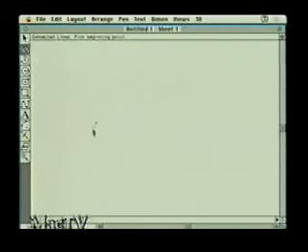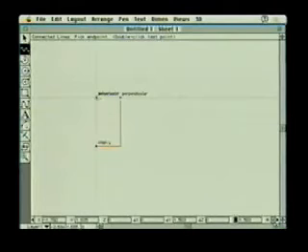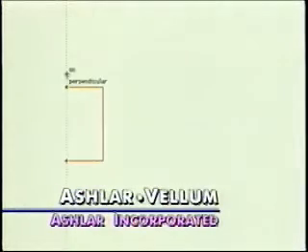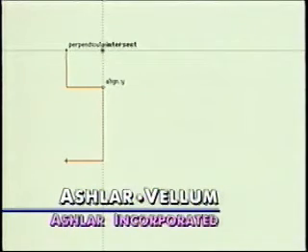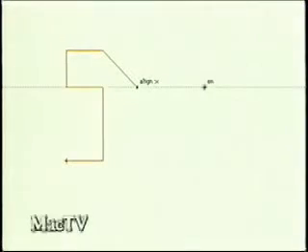Let's see why this interface has been voted by the SPA as one of the best interfaces in the product. The big thing about Vellum, again, is the Drafting Assistant. That is used to automate aligning and constraining things. Like when I get a horizontal line, it snaps automatically with no extra commands. As I move up, I get a vertical line automatically. As I come back across, it also sees logical points such as this intersect, and it puts up all these words so I can see exactly what I've got. So it's showing the intersection, the x and the y and the perpendicular. I can pick that point and then move up, and all sorts of alignments become available to me. As I slide down, I get this alignment. As I slide across, I get an exact aligned horizontal line.